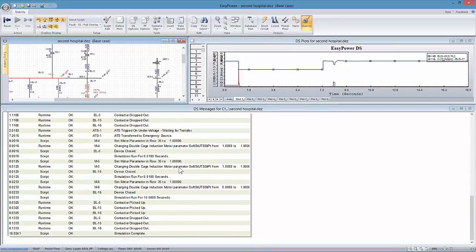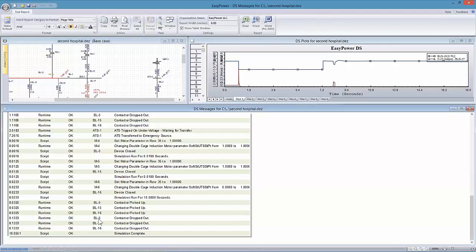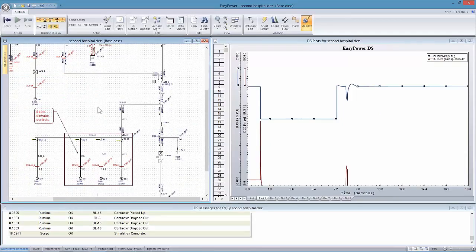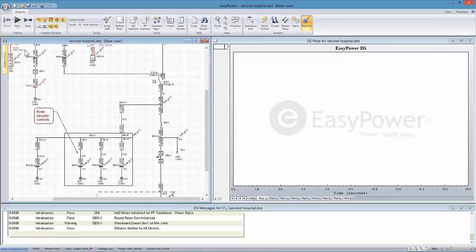We don't know exactly the mechanism that caused the failure, but we can go through and look at specifically. It's just our contactors dropping out of the motor starters because they didn't have adequate current from the bus to be able to sustain the motor start. Okay, nice exercise, not necessarily for facilities, but for people that design motor controllers.